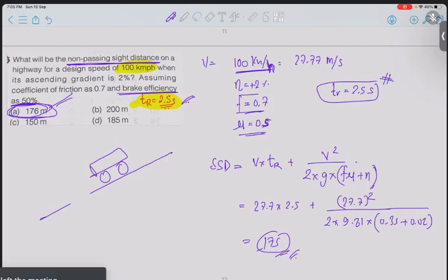Sir, I do have a question. This is actually regarding the super elevation. When we are calculating the minimum radius beyond which there is no requirement of super elevation, but still we are providing the super elevation in the form of camber, for that calculation, whether we need to take 100% of the design speed or 75% of the design speed.